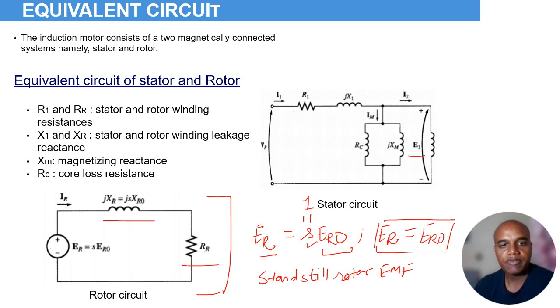Here we don't have anything like the stator, which has the parallel branch in its equivalent circuit diagram, because the magnetizing component is being done by the stator itself. Or I can say that to produce the electromagnetic field or the magnetic flux, only the stator winding is used. The rotor doesn't have any part in that. So therefore, we have to account only for the resistive drop and the reactive drop. XR represents the reactance, and similarly RR represents my rotor resistance.